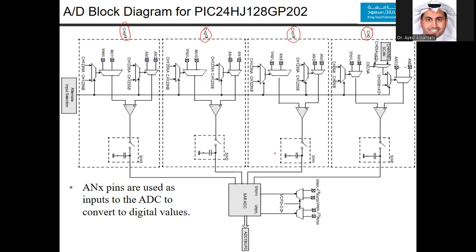This is actually an architecture choice, and looking at it in a different way, for channel 0 you have everything that you can choose from. So if you choose 12 bits, it should give you all the possible options. And for the other one, you have from AN1 to the VREF. That's the choice that they made for the other 3 channels that you can use.